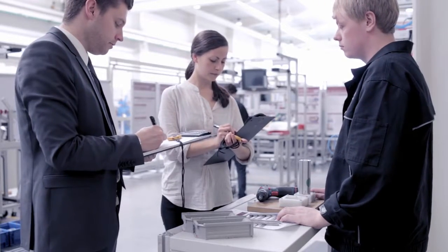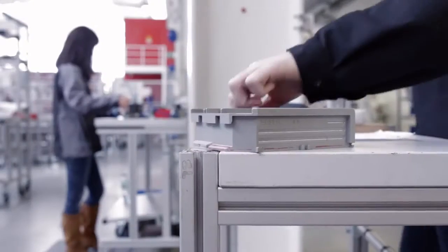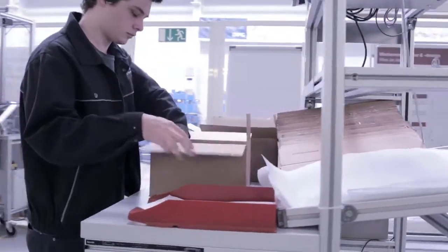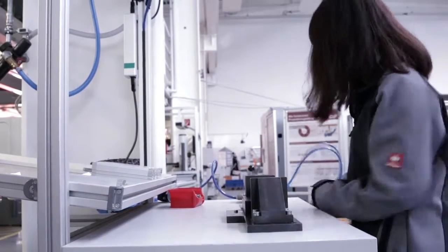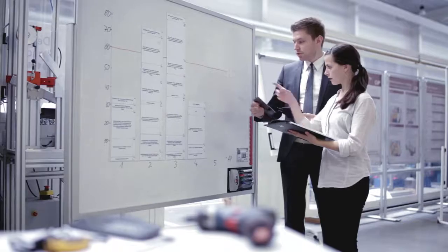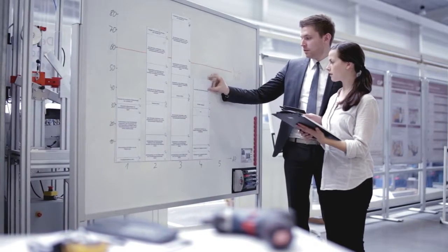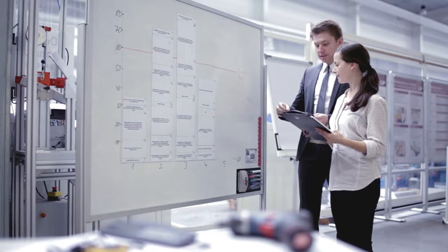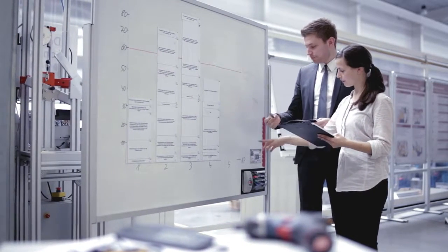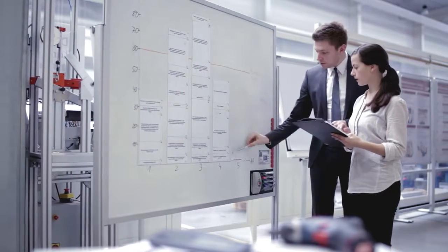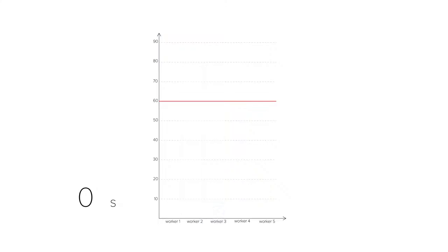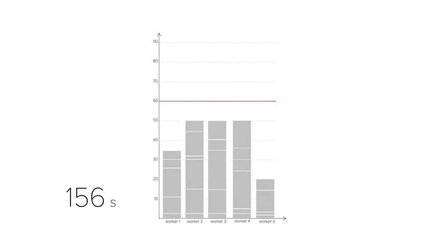In addition to value-adding assembly tasks, there are also secondary processing times for handling, checking, and packaging to be considered. The generation of these assembly times serves as the foundation for balancing workloads in the flow production. The determined process time results can be visualized in an operator balance chart. For each of the 5 workers, the steps carried out and their respective task durations are compared. The total sum of all assembly tasks leads to a process duration of 265 seconds.